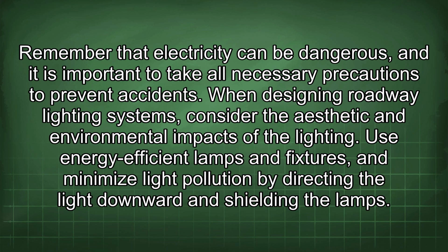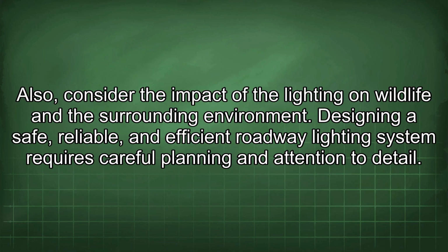When designing roadway lighting systems, consider the aesthetic and environmental impacts of the lighting. Use energy-efficient lamps and fixtures, and minimize light pollution by directing the light downward and shielding the lamps. Also, consider the impact of the lighting on wildlife and the surrounding environment.